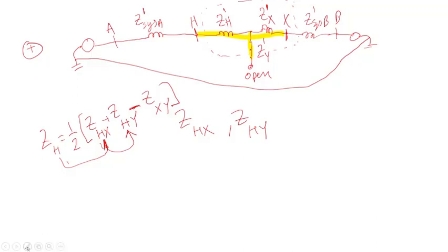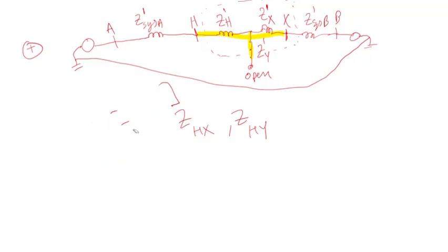That can be another video, but I just want to mention how you get the T model for the positive sequence. In previous videos, I talked about how to calculate the T model for the zero sequence impedance, but keep in mind that you can do the same thing for the positive sequence impedance.